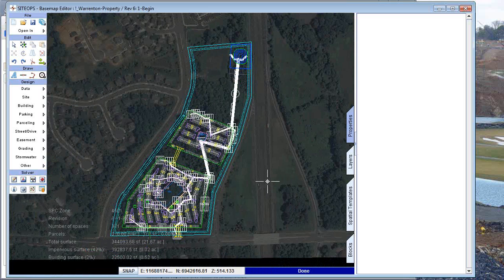And indeed we can. What I'm looking for are white pipes. Again, that means I have drained the site. There is no standing water. I met all cover conditions. I met minimum pipe slopes on my pipes. I've sized my pipes and added in intermediary clean out manholes and things like that.